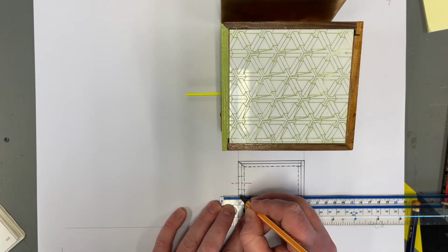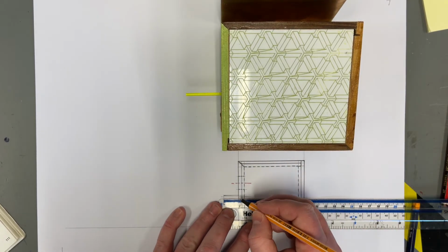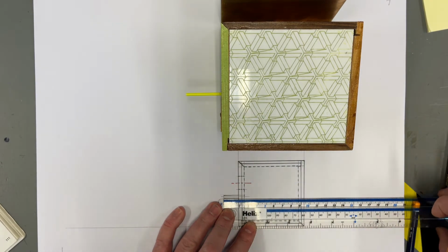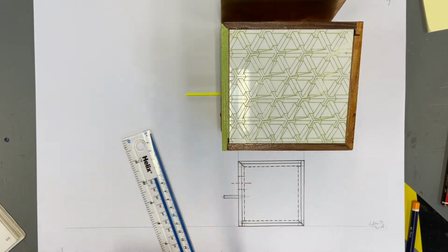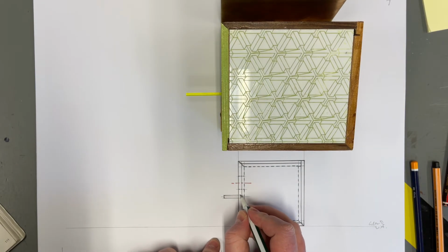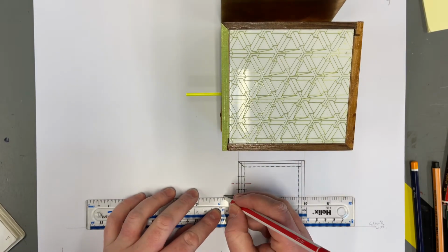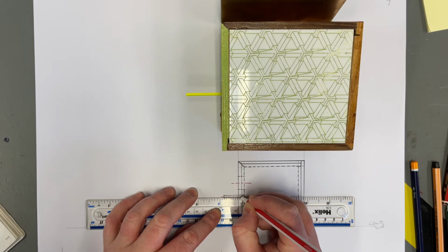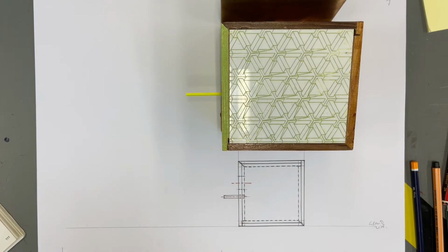Now, if your birdhouse is smaller than this one, if you've designed it to be relatively wee, then there's perhaps no need for you to scale the drawing down in any way. If you could fit all views at 1:1 scale onto the sheet of paper, then please do that instead. Makes life a little bit easier for you. So hidden detail lines in for the perch and a center line, long dash, short dash, through to show us where the perch would go in the object.